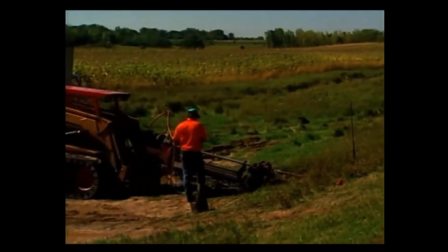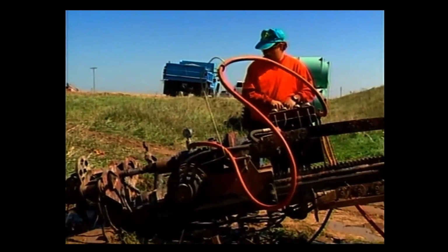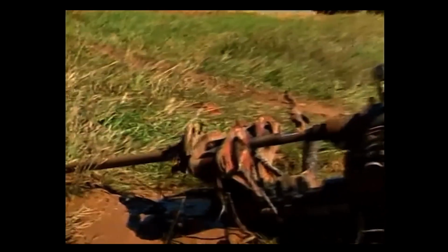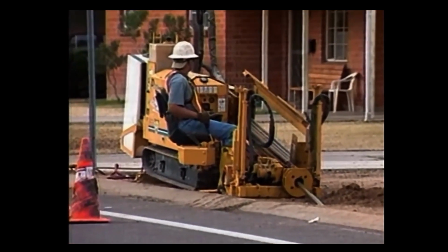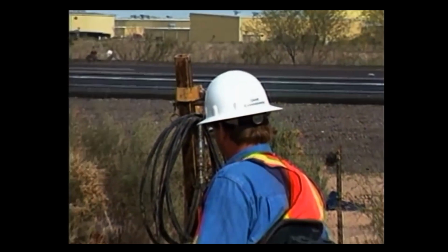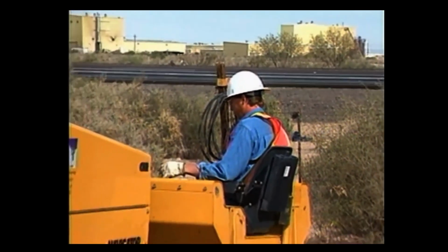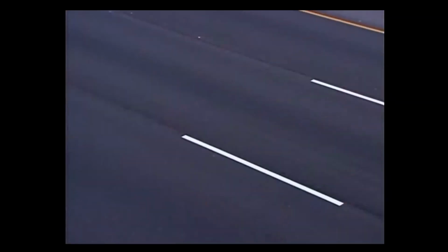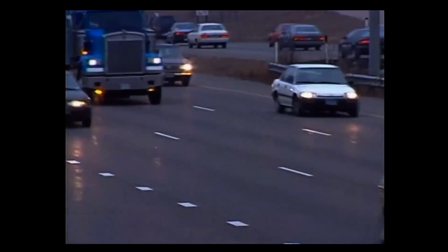You install the microloop probes into 3-inch plastic conduits under your roadways, using standard trenchless or horizontal directional drilling under existing pavement, or open trenching techniques on new roadway construction. It's the same method contractors use to route fiber optic communication cables and other utility lines under roadways. As a result, there's minimal impact on traffic during conduit installation, and your roadways remain intact.